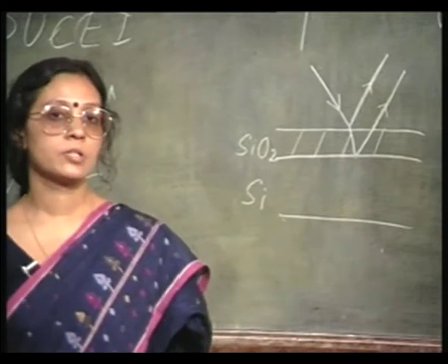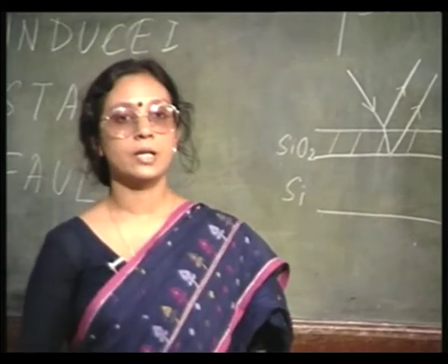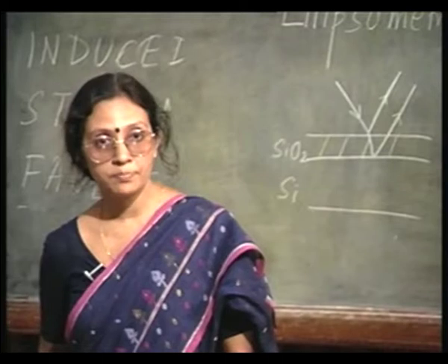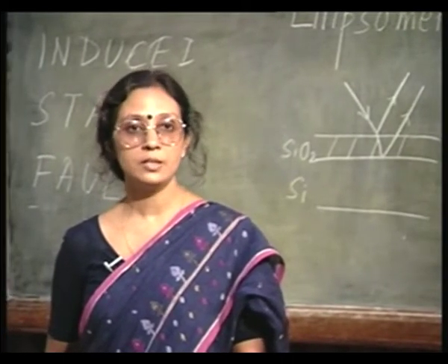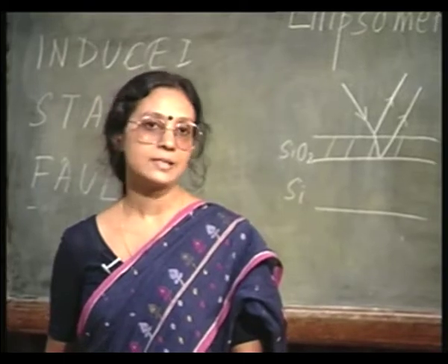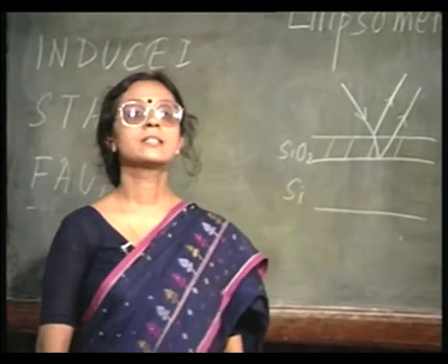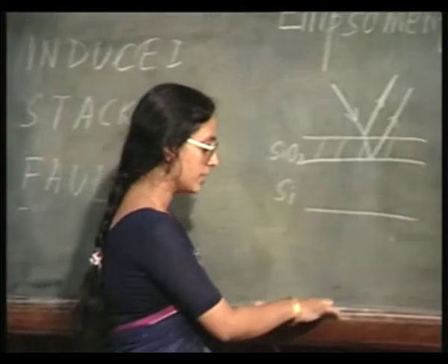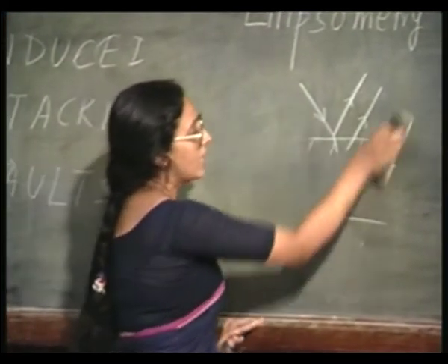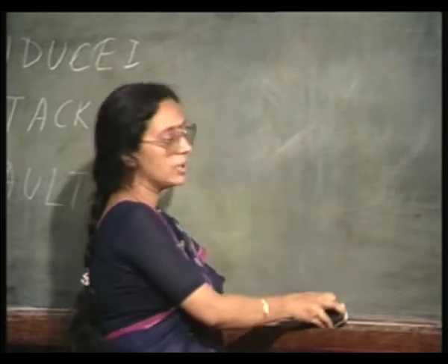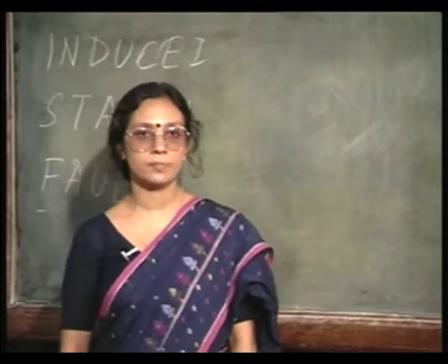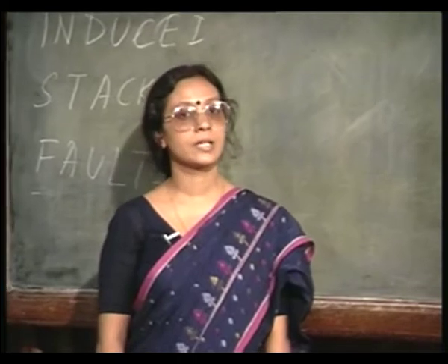In the laboratory, however, we use another very simple and electrical method of determining the oxide thickness, and that is done simply by taking the CV characteristics of the oxide. You know, if one has a MOS capacitor, then in the accumulation region the capacitance of this MOS capacitor is going to be the oxide capacitance.